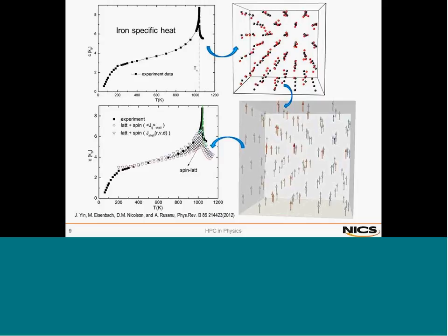And when we look at that, what we found is that in most calculations, people assume that at this temperature, the structure of iron is still a perfect BCC structure, as indicated by this black sphere. But as a matter of fact, at 1000 Kelvin, you can expect that there will be lattice vibration near the equilibrium position. So there will be a thermal displacement for these iron atoms.